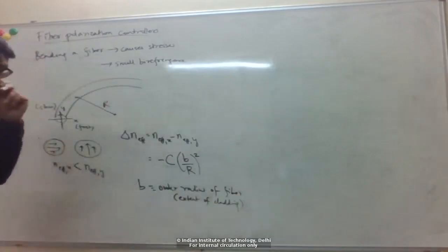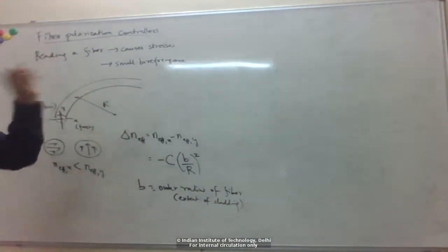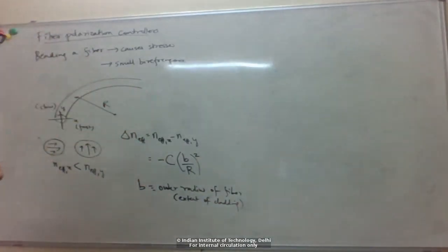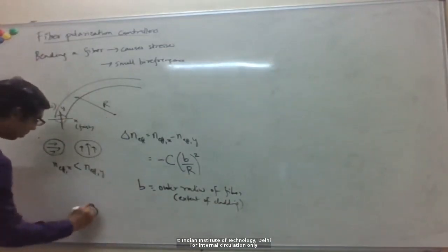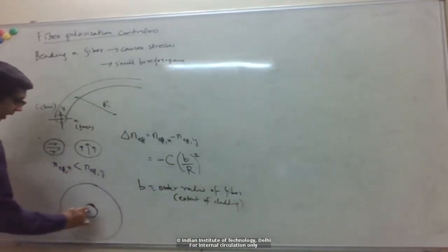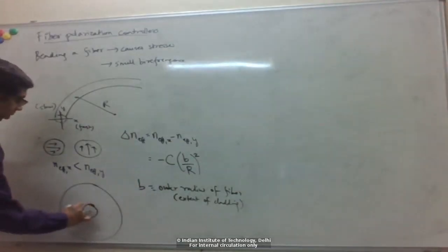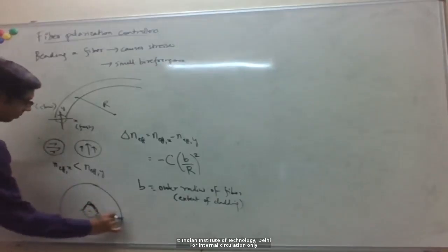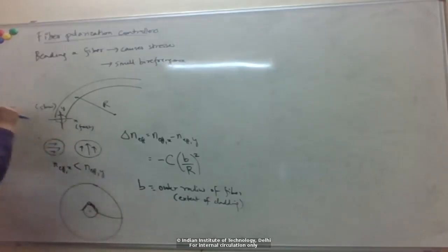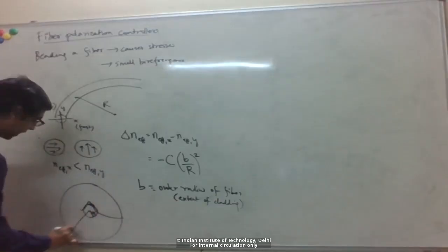So far we've sort of neglected the extent of the cladding, right? We just always take the core size and then say it's cladding everywhere outside, but of course the fiber has some finite size, right? So you have some core, and then there's a cladding which we sort of assume just extends to infinity, but actually it has a finite size. And the approximation of this extending to infinity works because the mode profile is basically 0 by the time you come here, right? So it doesn't matter what's happening here. But this is a core size A, right? And then there is a cladding size B.